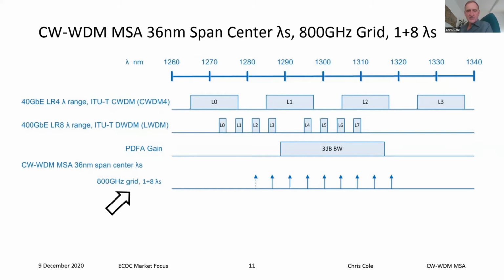There's other advantages to this kind of a grid, which has to do with photonic integration. One other feature of this grid is you notice this is 1+8. So there's actually 9 wavelengths specified. So what you have here is 8 data carrying wavelengths and then an auxiliary wavelength that, if you want to have a synchronizing or clock signal or something like that you want to distribute, that's available in a specified fashion. Or you could just use it for carrying more data. But it's anticipated that the data carrying wavelengths will be the nominal 8.